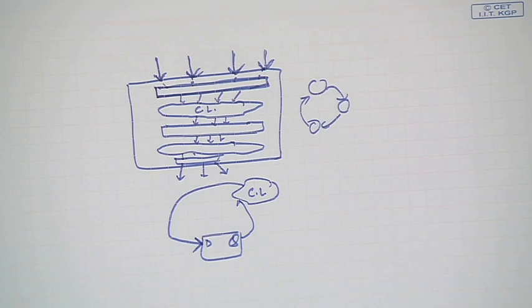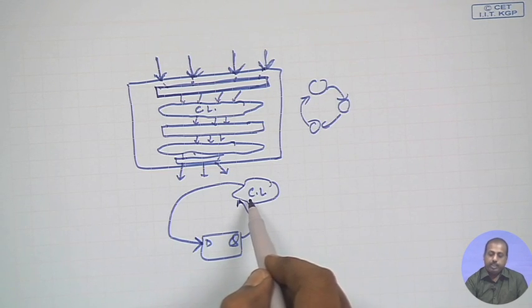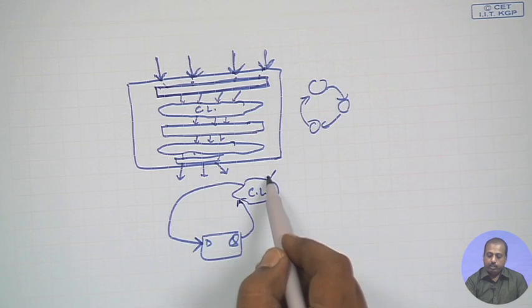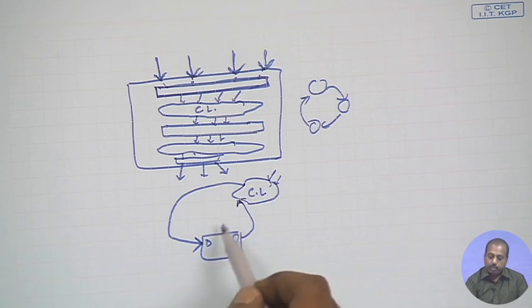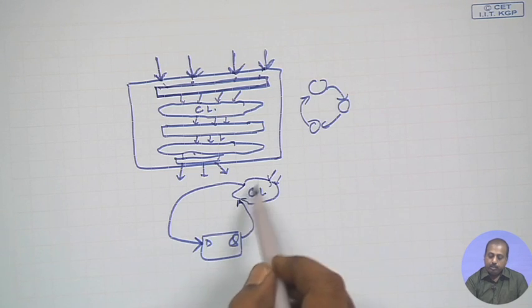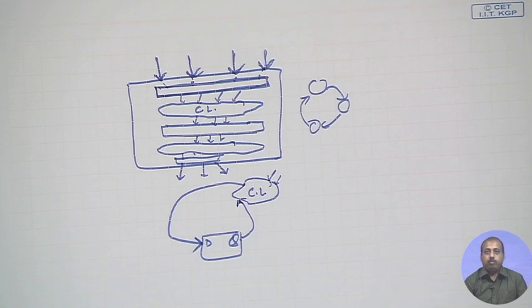In this case it becomes difficult to control this particular flip flop, because to set this flip flop to some value, I need to set the combinational logic inputs to some value, and for making the combinational logic give a proper output for Q, I again need to set this Q value to some value. So, it becomes a circular logic.